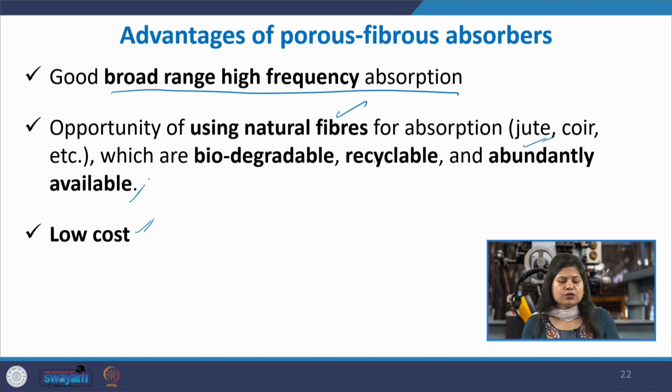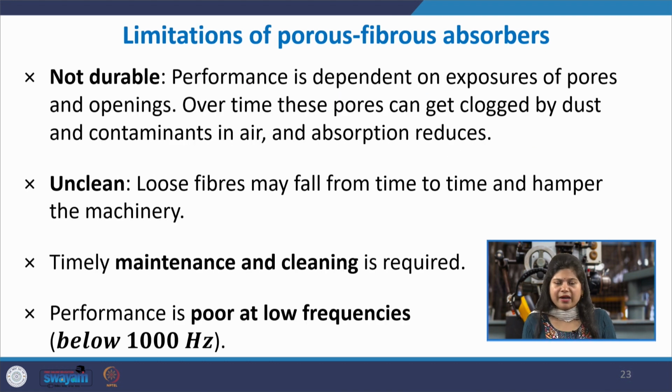All of this is advantages of the porous fibrous absorbers, but obviously there would be some disadvantages, and as a noise control engineer you have to decide, based on your application, whether they suit your application or not. So, what are the limitations we have? They are not durable: their performance is dependent on the exposure of the pores and the openings on the surface.